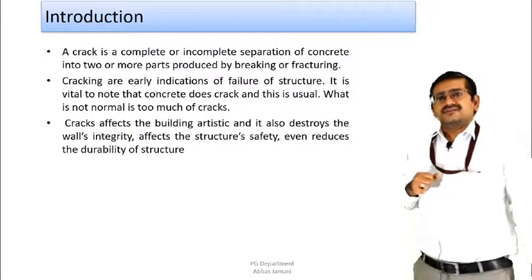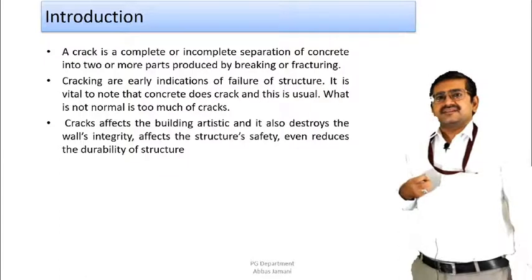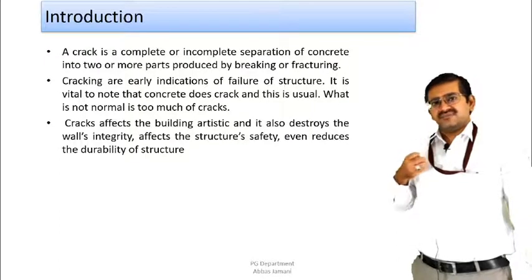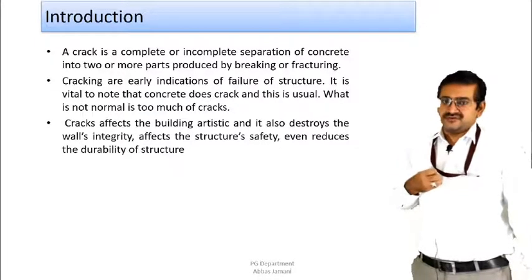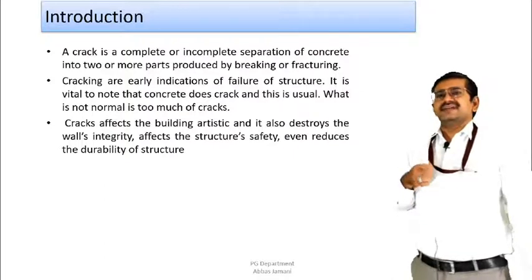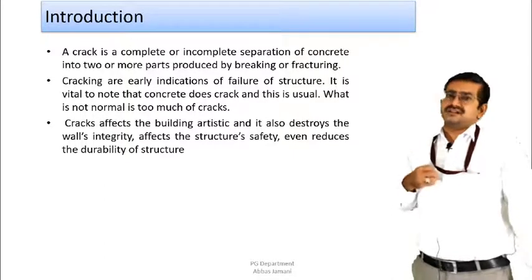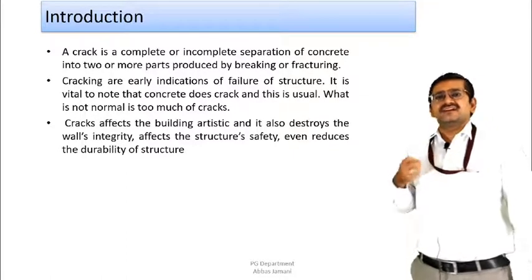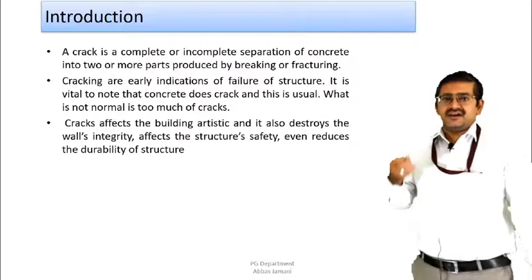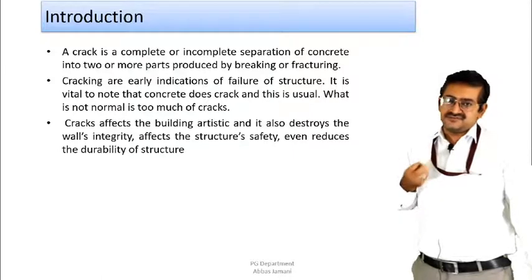Now, it is important to note here that cracks may be visible in nature, but when you see these cracks on the surface, it is not necessarily always a cause of worry, because you need to identify whether the crack is a structural crack or a non-structural crack. If it is a structural crack, then the possibility is there that it is going to dampen the safety of the structure.